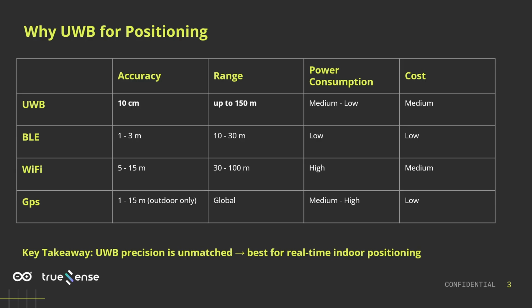Why is ultra-wideband good for positioning? It's mainly because of the resolution that you can get. We have been hearing in the past about localization systems implemented with Wi-Fi or via BLE beacons, but they have a big flaw. The resolution is in the order of meters, while in the case of ultra-wideband, we're talking about a resolution of ±5 centimeters and 3 degrees in the measurement of angle, because it does not only measure the distance, it can also measure the angle of arrival of multiple devices in front of it. So I will skip the numbers, you will find this in the presentation.